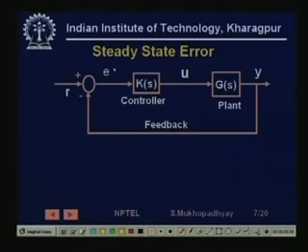So if you have performance degradations which are persisting during that phase when the set point is held, then that is generally considered much more serious than errors that can occur when the set point is changing or immediately after that time for a short duration. So we would first like to ensure steady state performance, and the major consideration for that is steady state error.